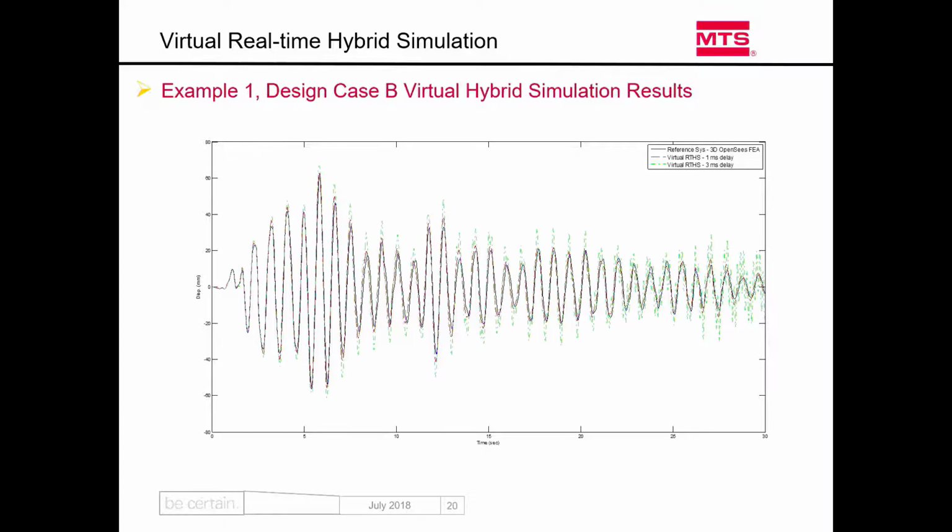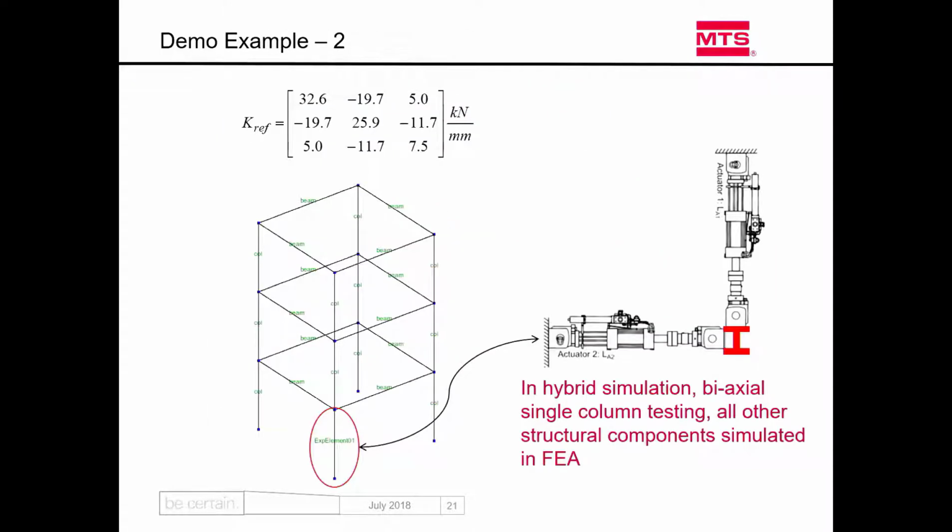Now stable, 3 milliseconds start to show this kind of local instability. We actually predicted that, remember, using the equation of motion. We said 3 milliseconds was about the borderline. And if you go to 4 milliseconds, of course, I cannot show it here, it just blows up. So this is a kind of virtual testing validation of the equation of motion we constructed.